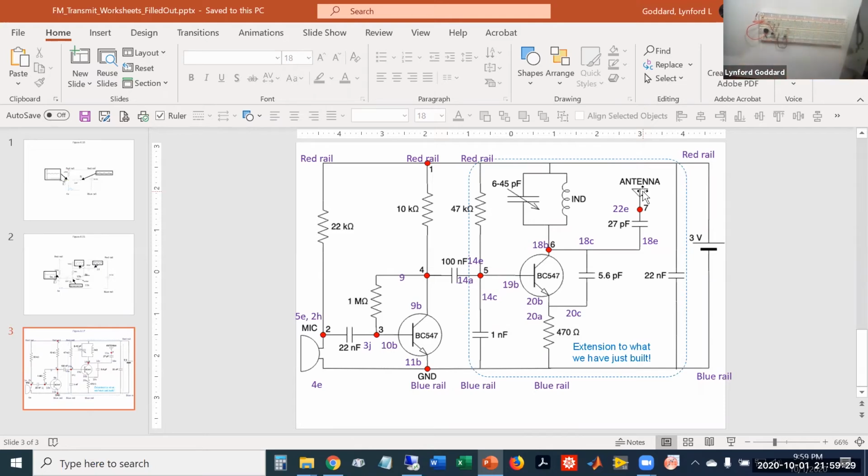Okay, it's kind of going in, but I'm not confident in it. So I'm going to remove a few more strands. And I'm going to twist it a little bit more. Because every connection that I make, I have to ensure that it's actually connected inside the protoboard. So I need to make sure that things plug in. So you can see it's a little bit thinner now. Make sure that things actually plug into the protoboard.